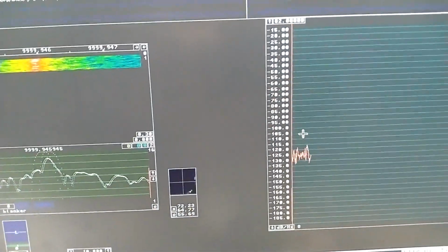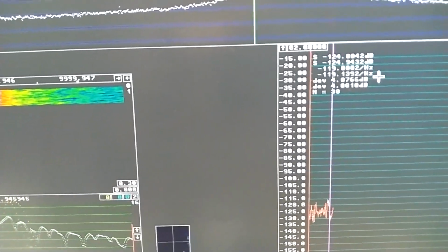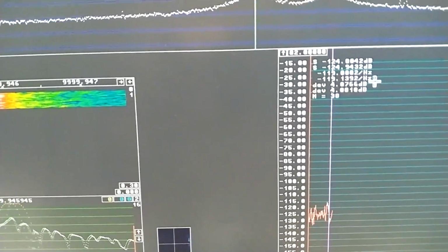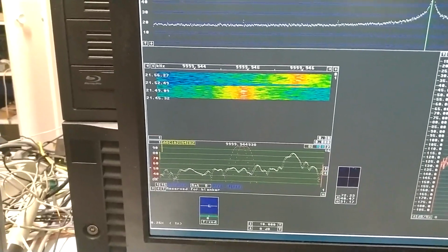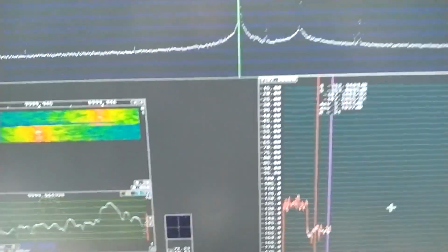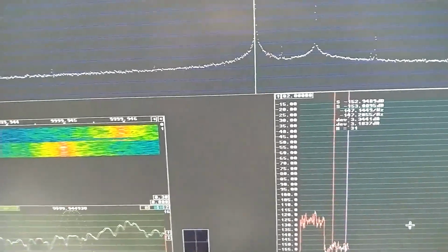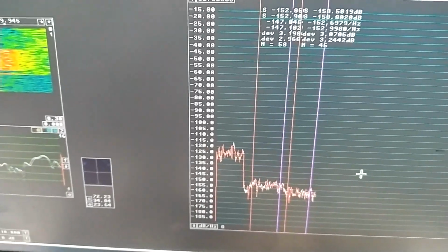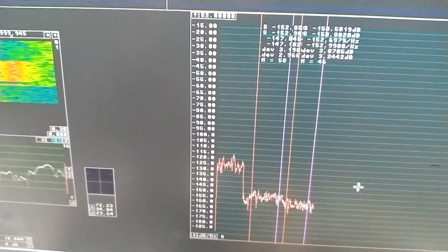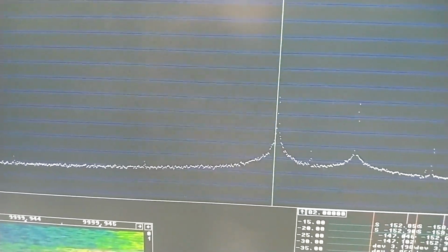The level I see is minus 119 dBc per hertz. Now I look at an offset of 1 hertz, and there I see minus 147.2. At 2 hertz offset I see minus 152.8 or so, and it's at this position on the peak.